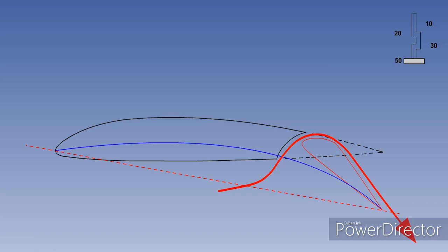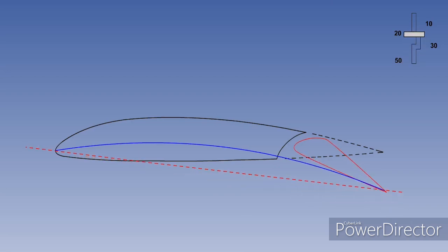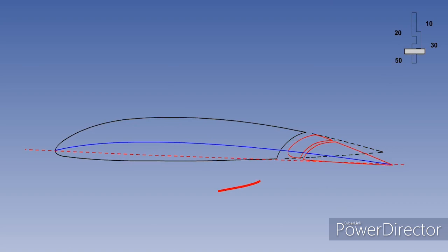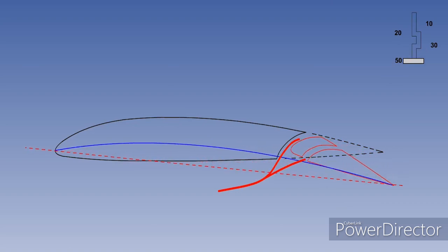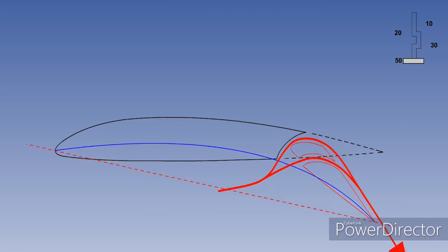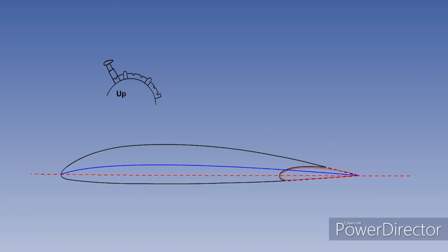Therefore, the slotted flap can be lowered to a larger angle before airflow separation begins. This allows a greater increase in CLmax with much less drag than is possible with either the plain or the split flap. A slotted flap can have more than one slot. Double or triple slotted flaps are usually fitted to larger aircraft, which can offset the higher weight and greater complexity against the increased efficiency. The most efficient type of trailing edge flap is the Fowler flap.